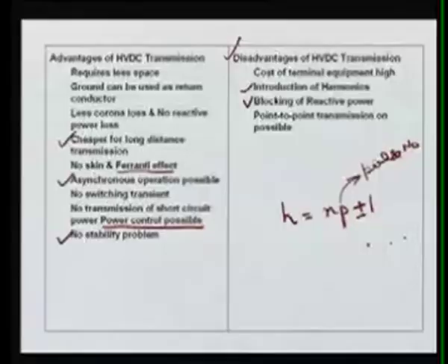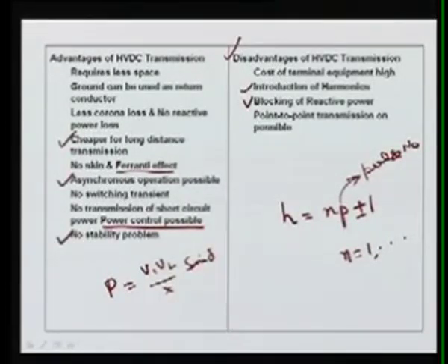Sometimes in emergency cases, let's suppose there is some generator outage or some fault, at that time we may require some reactive power support from area 1 or area 2, but it will block here. So it is not possible to transmit the reactive power from area 1 to area 2 or from 2 to 1 during the emergency condition. So it blocks the reactive power. But in normal practice, we don't allow reactive power to flow from one remote place to another, because reactive power is a localized concept, and it is related to the voltage of the system.